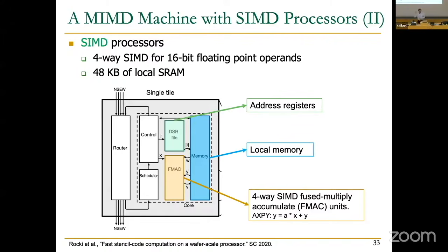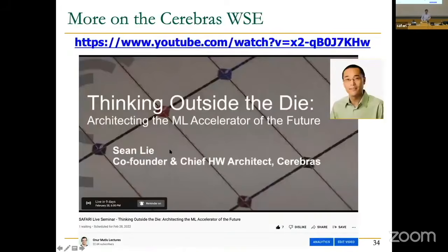Essentially, that's what they're doing. They're converting convolutions to matrix multiplications and doing them using these four-wide vector operations or SIMD operations. Okay, if you're interested, there's a lot more out there that talks about this. But I wanted to point out that SIMD operations exist in machine learning accelerators, specialized for machine learning as well.